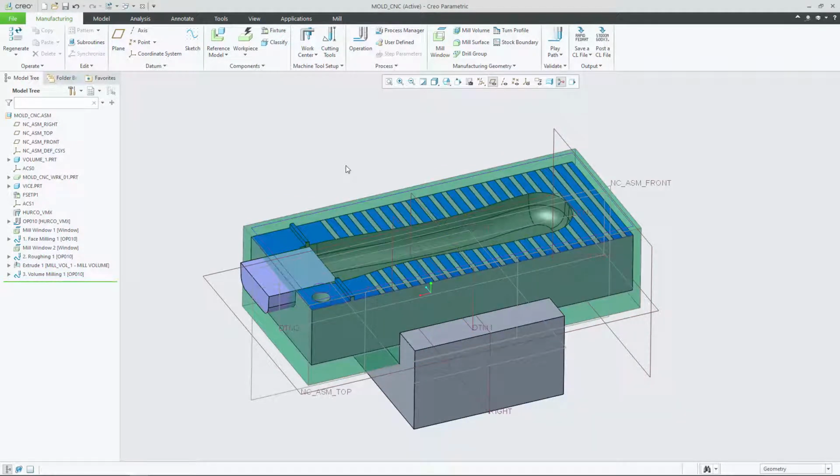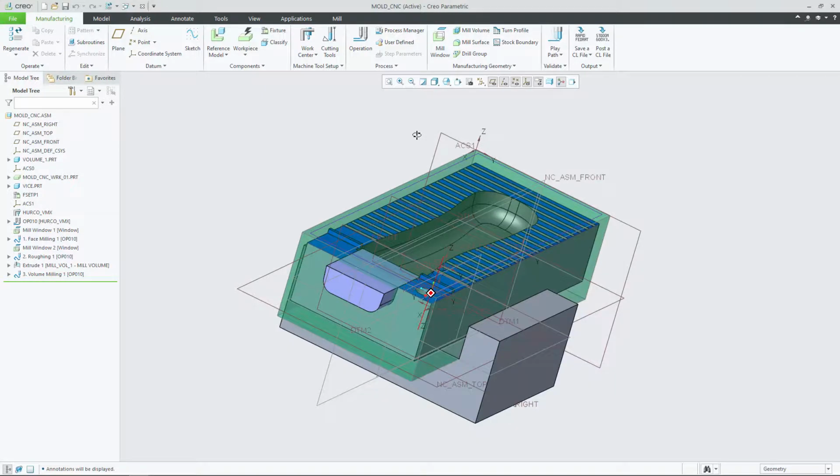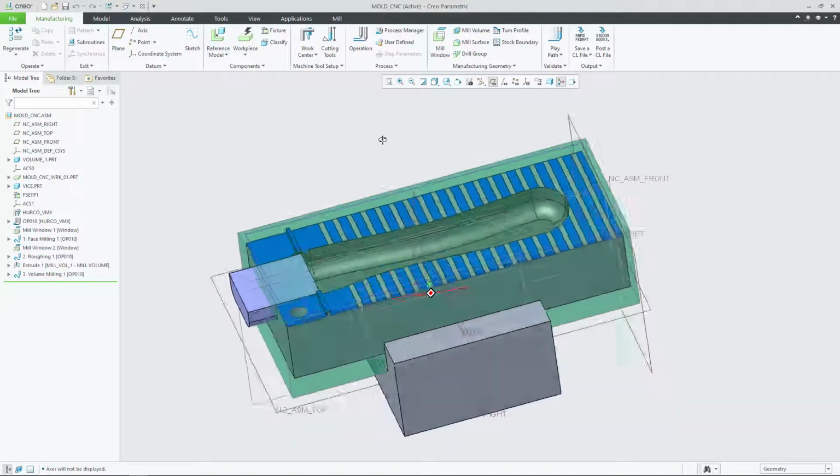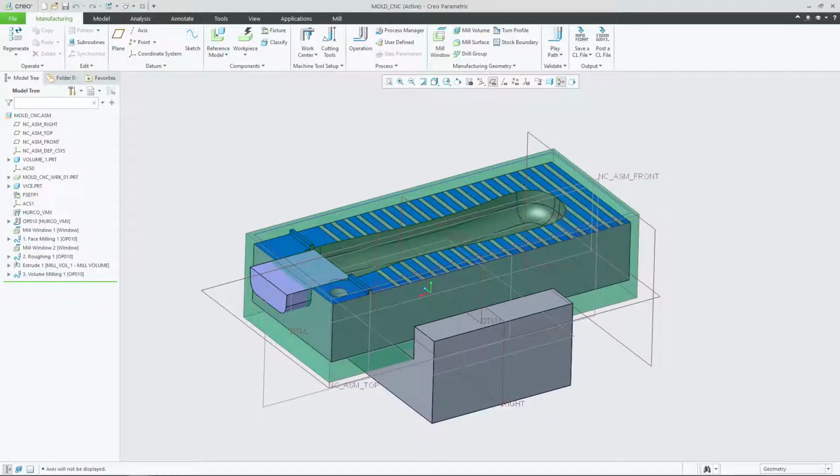As I loaded that in, I turned off the display of some of the datum items. So you can see that I've turned everything back on. What is most useful to us here is to be able to see the planes, certainly, and everything else you can just turn the visibility of it to off like that, so it tidies up the display a little bit.